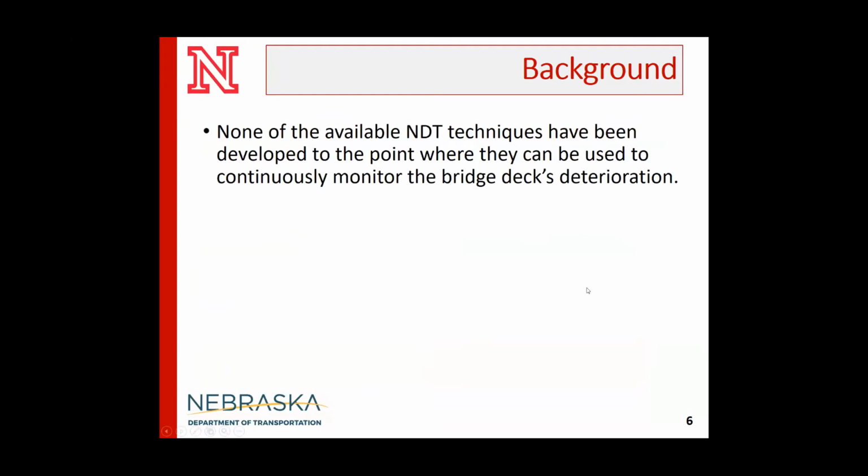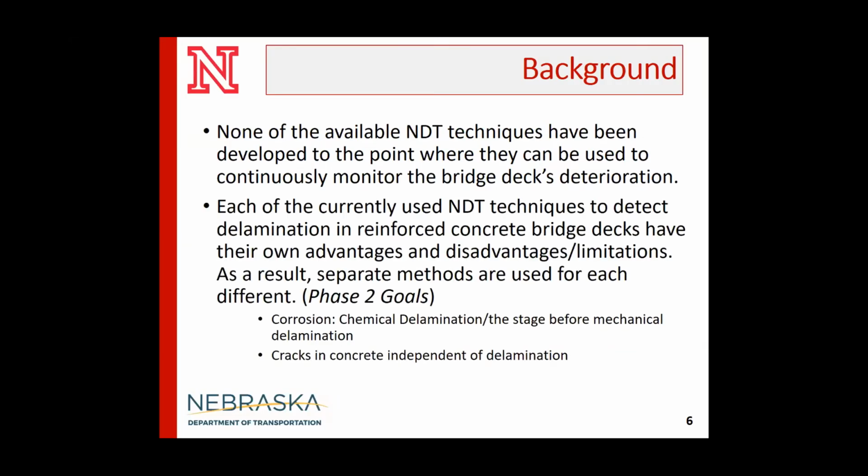And the other issue is most of the NDT techniques are for instantaneous measurements for existing structures, so you don't really monitor the deterioration over time, and this idea has the potential to do that. And finally, we all know, and the previous presentation was a great leeway into that, a lot of techniques are strong in one way and can detect certain types of flaws better than the other ones.